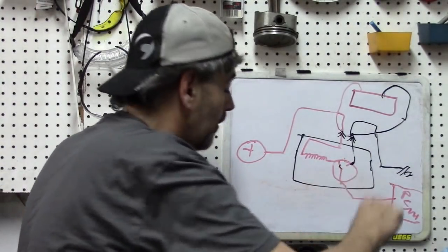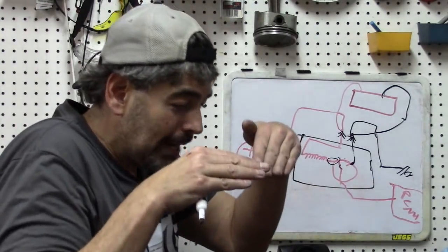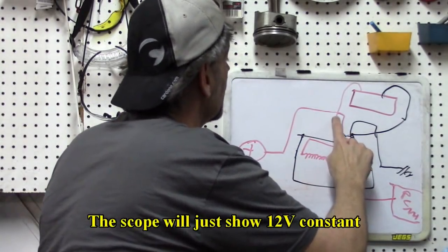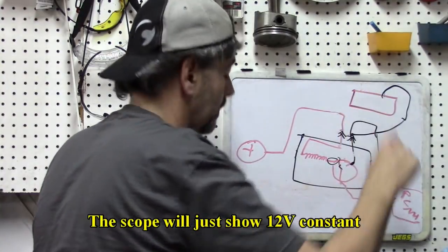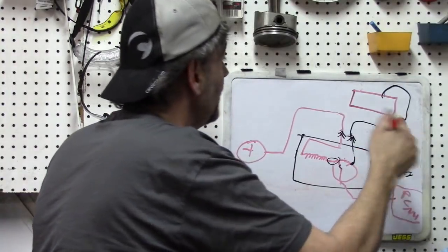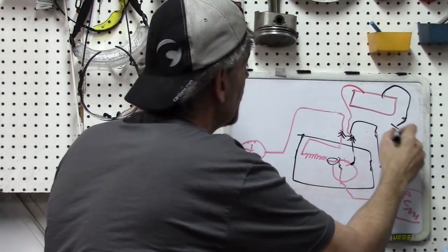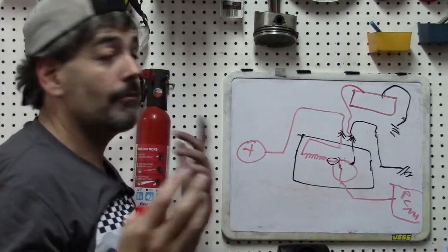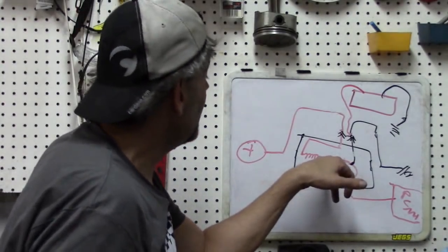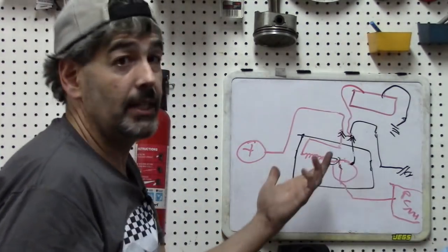It is here. That is where that voltage spike phenomenon is occurring. We can't measure that because we would have to go inside the coil. So we're missing it. Same thing over here. If we were to move, like we did in the last example, our scope positive here, and then send this one just to a chassis ground, okay, we're going to have the same problem. The problem is your voltage spike that you're looking for is happening here. This leg of the transistor is open, so you're just reading an open against ground.